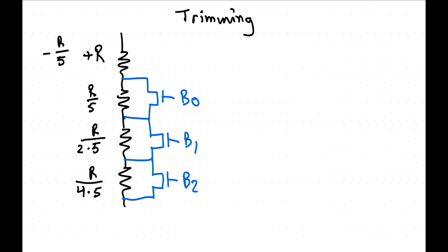And the other thing is that once you have determined that, then you've got to store that information somewhere. In most systems, it's not a big drama because you normally have some non-volatile memory somewhere. But if you're making just an op-amp, you don't have that. So it's better if you can design your circuit in such a way that you do not need to calibrate.